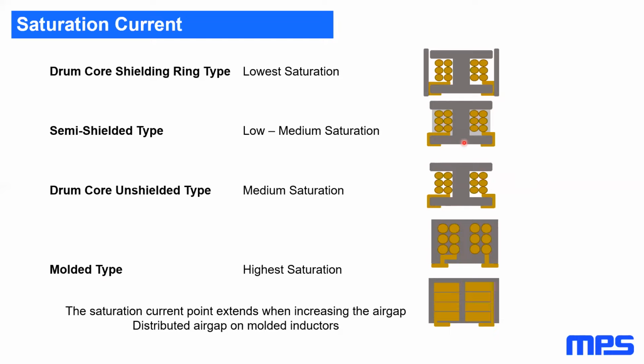And depending on the material you are using, you will also have different core losses. Ferrite powder materials naturally have low core losses. But if you are going for higher frequency, maybe it's better to use these kinds of components. So it's a matter of really many parameters. It also depends on the temperature. The molded inductors will have better thermal performance than the drum core types.